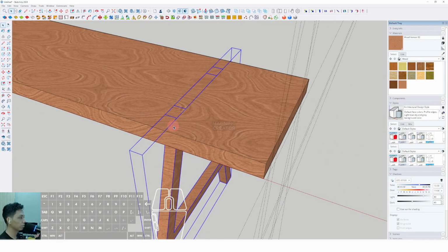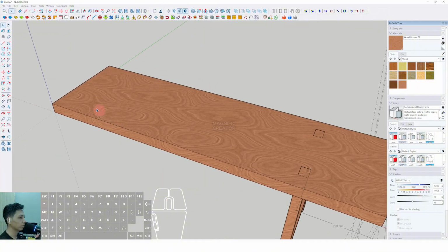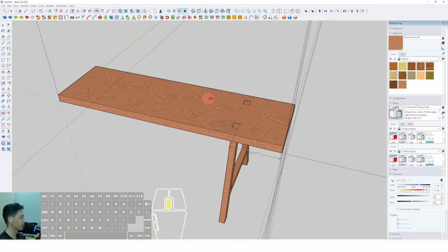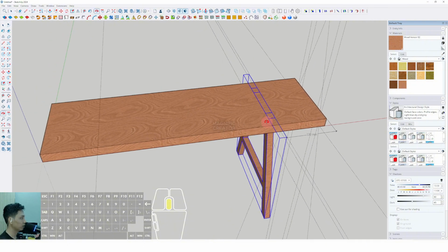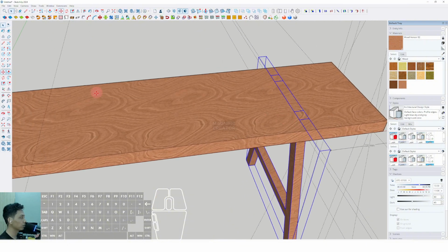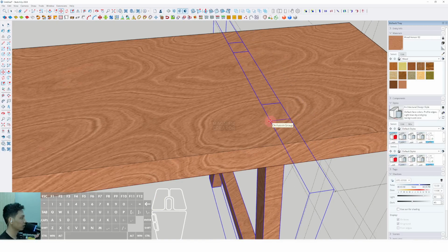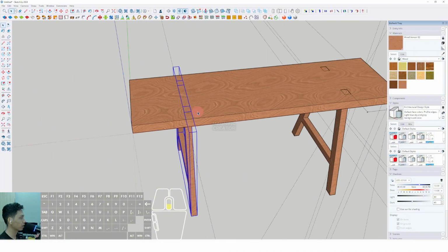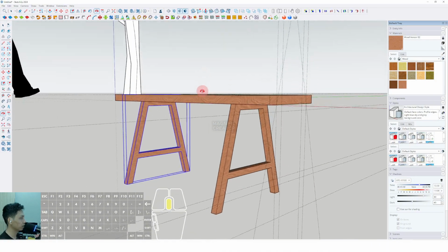Okay, then we can see about the distance. Click from this corner until this corner, we can type 220 and we can click this tape measure tool, click this edge and we can type 220 again in here and enter. Then we can click this object again, select move, click the corner and tap control and place to this guideline.